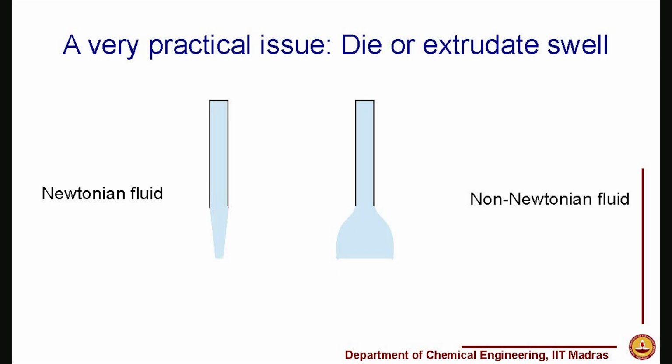And of course, this is as long as we maintain a flow rate which is low enough that the jet does not break up and form a spray, in which case it starts spraying everywhere. So, we are still looking at a jet nicely following, and usually the diameter of the jet would be of the same or similar order of magnitude and slightly smaller. In fact, it is about 80 to 90% of the diameter of the tube, depending on the conditions.